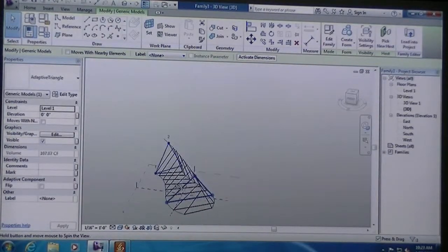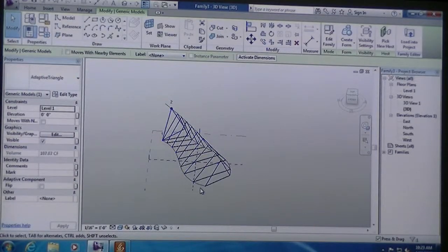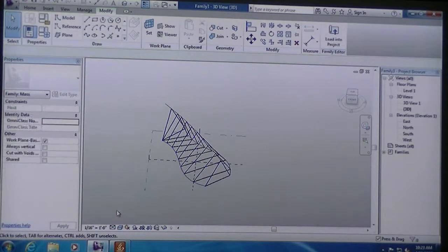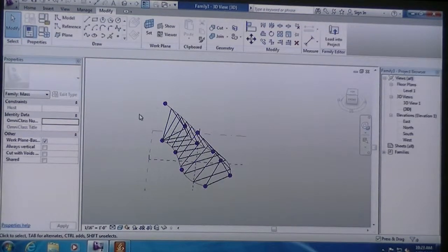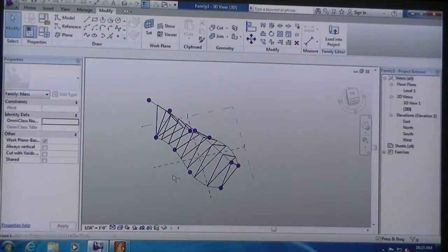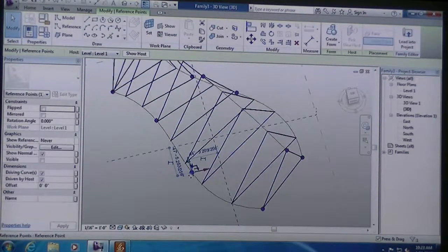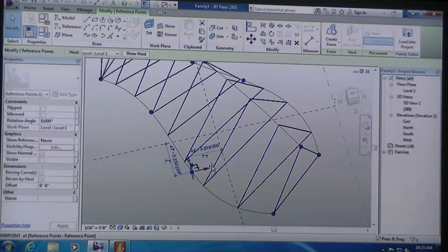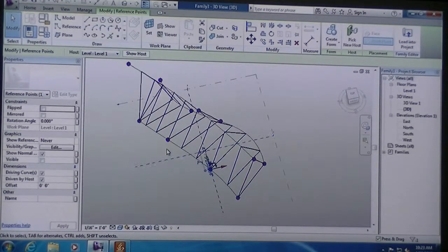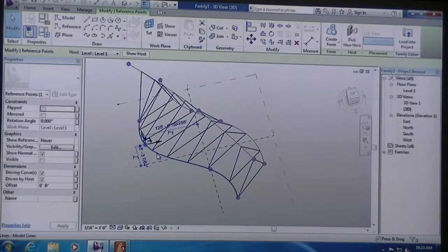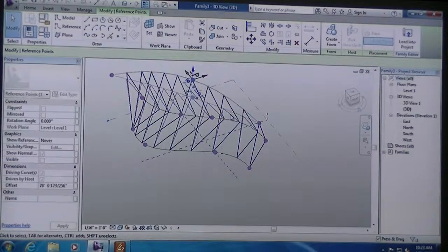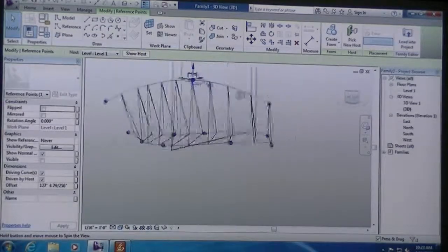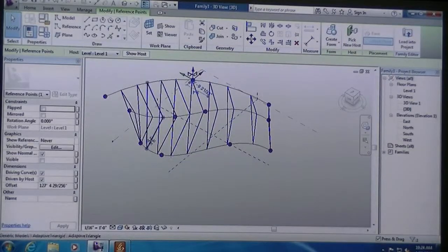Now what's important about that is if you made this particular shape and you've got all this structure here, and you later decide, now I have to turn on my points again, if you later decide to change the form of your spline, so if I select one of those points that create that spline, and I'm going to move it in, as I make changes, my adaptive component is also making changes as well and adapting to however that adaptive component has ended up.